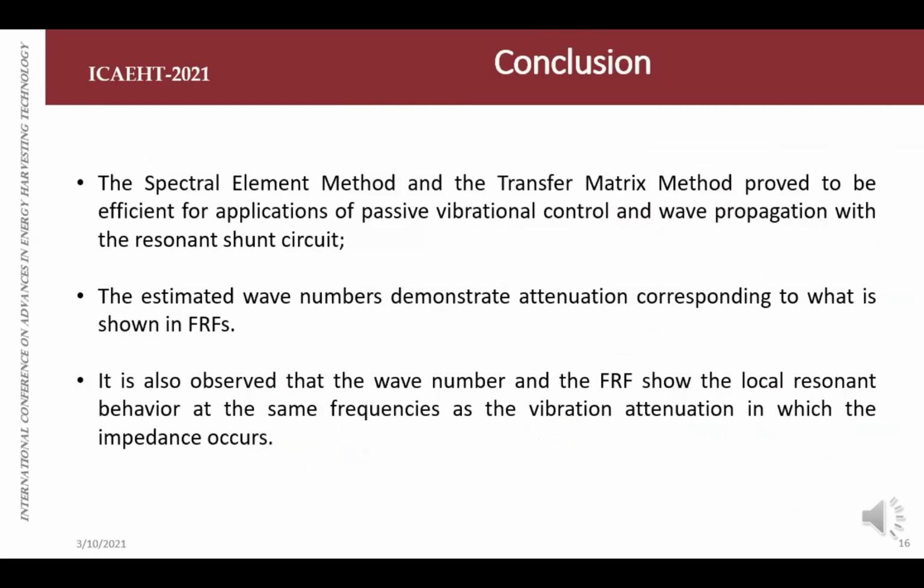The estimated wave number demonstrates attenuation that corresponds to what is shown in the frequency response function. It is also observed that the wave number and the frequency response function show the local resonant behavior at the same frequency as the vibration attenuation with the impedance occurs.